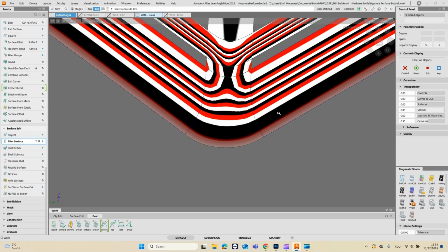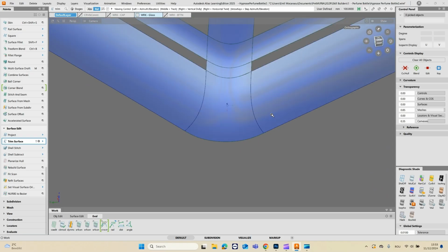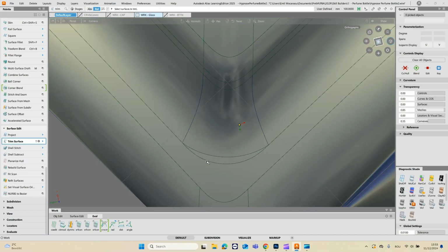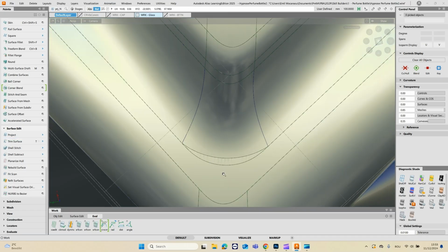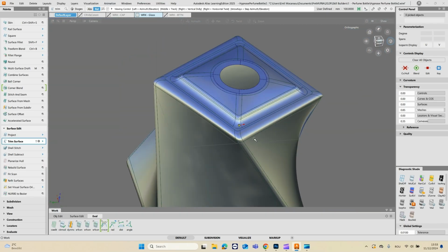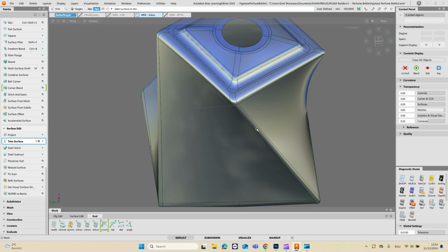So that's a quick and dirty realignment, and that's how those corners should start looking. Let's project normal to that surface, this edge there. Trim this back. Hopefully it doesn't crash. That's it. Save it up.